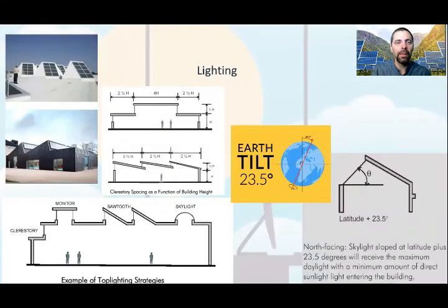Now we will see some overhead daylighting systems. They are very useful for lighting the darker parts of the back of the house. Skylights can be either passive or active. The majority of skylights are passive because they have a clear or diffusing medium, usually acrylic, that simply allows the daylight to penetrate an opening in the roof. They are often comprised of a double layer of material for increased insulation. They can be of any shape.